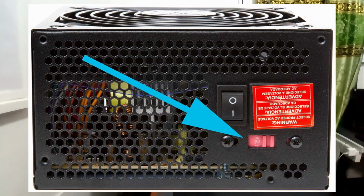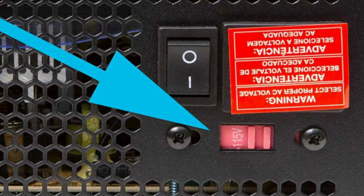If this device goes to a country that uses 110, before it can work, you need to switch this thing downwards. Do you see this switch here? You need to get a small metal and push it down. If you push it down, you turn it immediately into a 110 power supply unit. And that is the only way it will work in those countries.